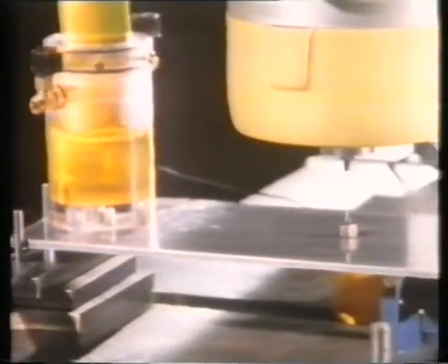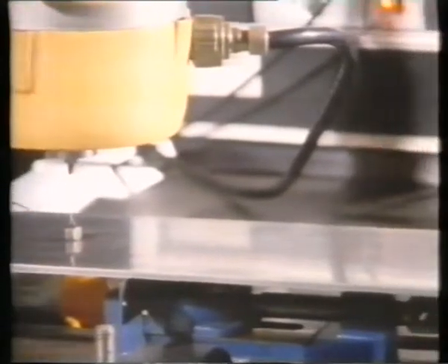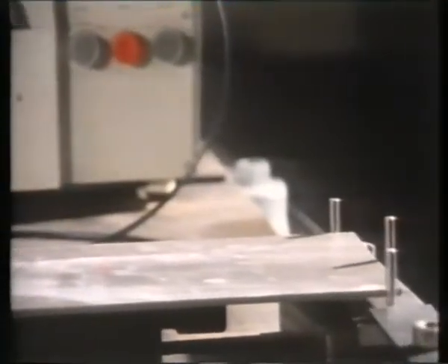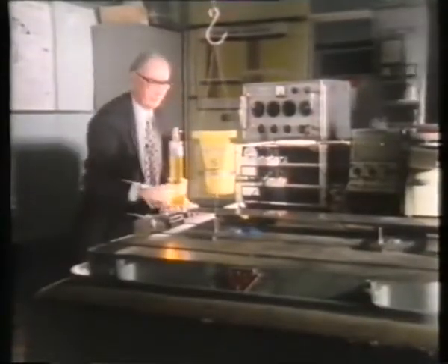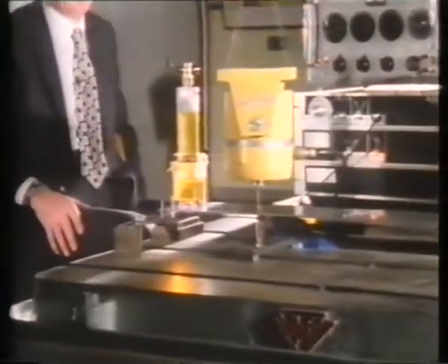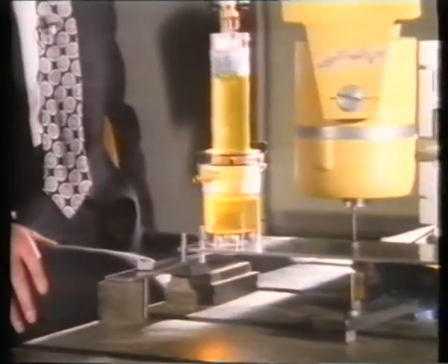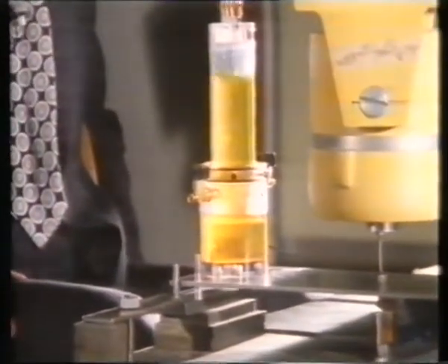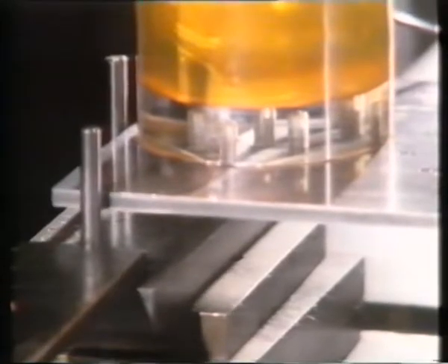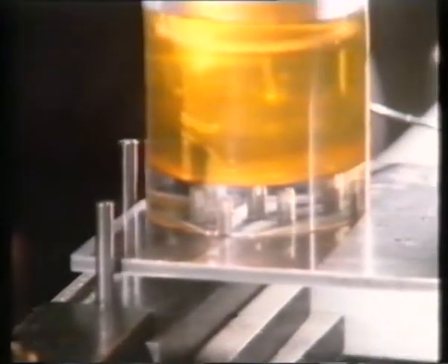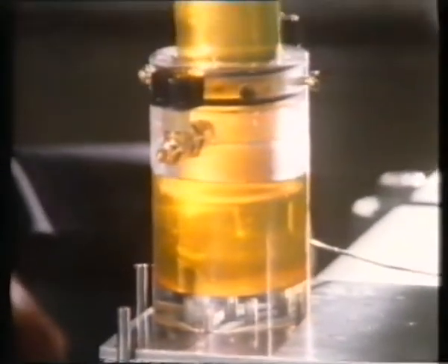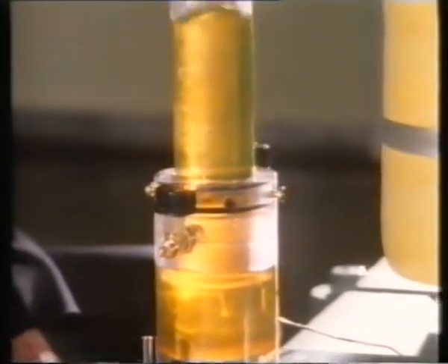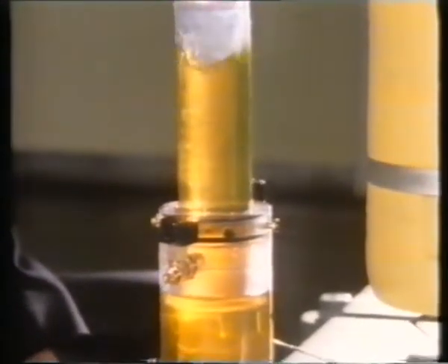The deck is the one-degree system, and you can see at this particular frequency the deck vibration is very small, not 100% reduced, but certainly very much smaller than it was. Whereas the second degree part of the system, the mass of water bouncing on an air spring, is vibrating in a fairly agitated fashion, indicating that the energy from the deck is being absorbed by the water here.